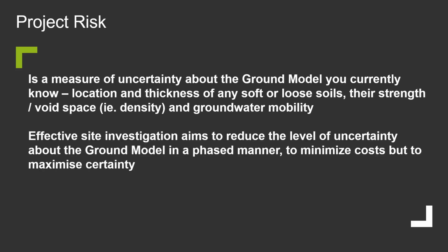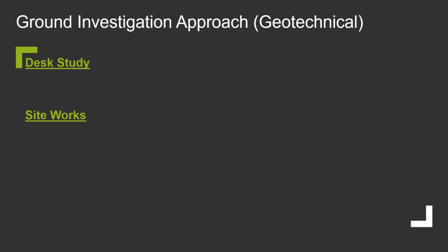And an effective site investigation will aim to try to reduce that level of uncertainty as much as we can in a phased manner. So not necessarily all in one go, but primarily a snapshot, if you like, to give an idea as a first stage, and then that gives a bit more confidence in the overall geological picture. With that in mind, the standard way in which investigations are carried out would be using a desk study approach and then site works.